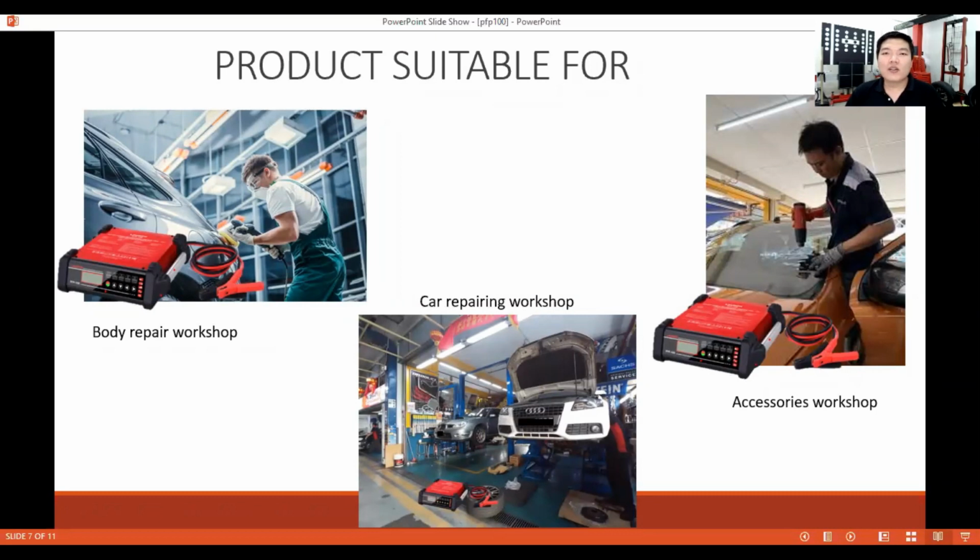They keep on changing the battery. When the battery is always opened and put back, the module will slip up. If it is like this, soon you will have many problems with the immobilizer. You have key immobilizer problems, you have control module damage problems, and so on. It will create many problems in body repair because of the battery voltage.